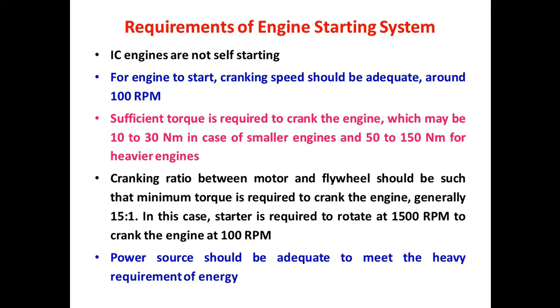Generally, IC engines are not self-starting devices. So to start the engine, a manual or electric cranking is required. Now, in that case, if that cranking speed is around 100 rpm, then the engine can develop adequate power required to bring it to full running condition.